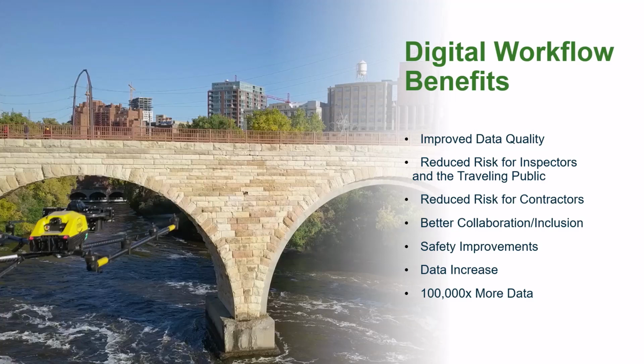Now, having that baseline moving forward, you're able to take this data and compare it to your next inspection. So you have a crack, it's a CS2, you know where it was, you know the length, you can go revisit it, measure the crack, did it grow, is it wider, is it progressing, things like that. So the data is much more granular, much more complete.